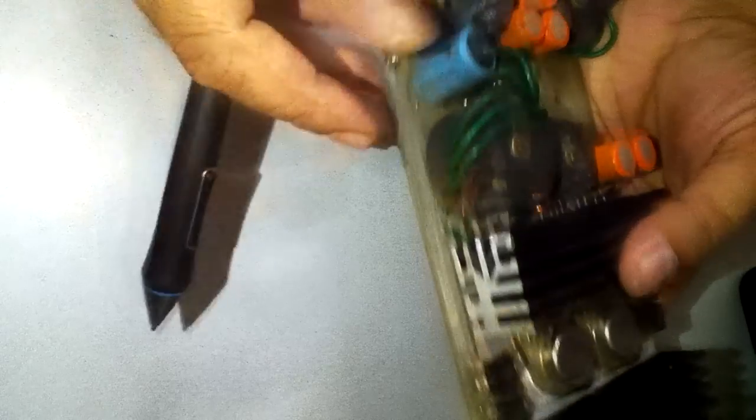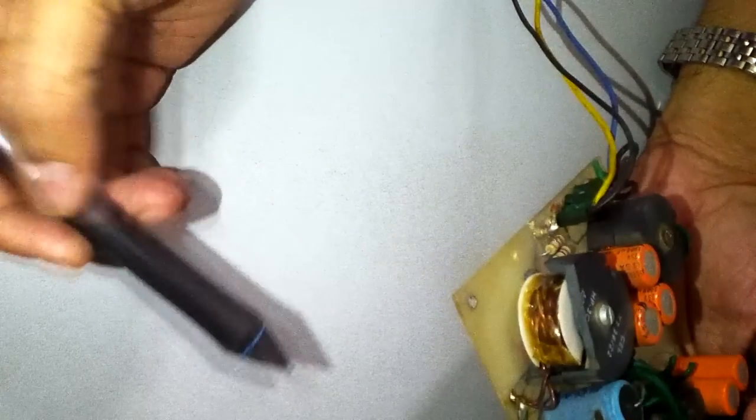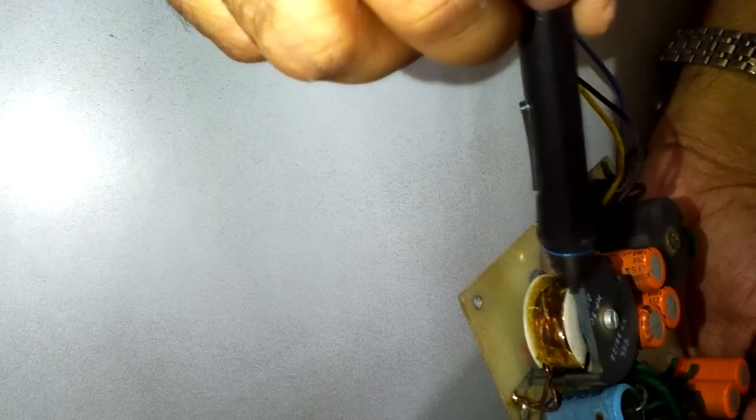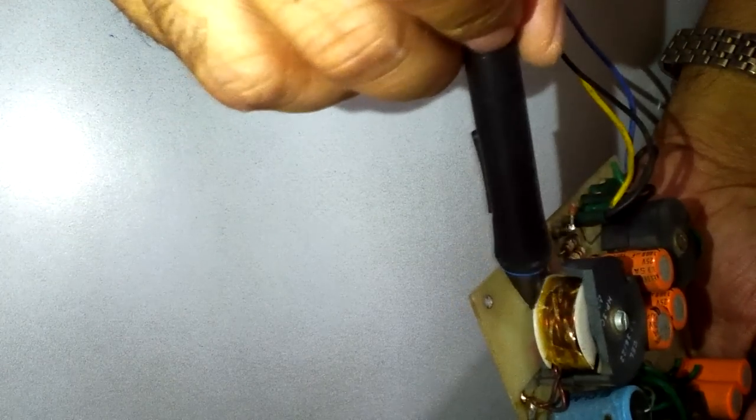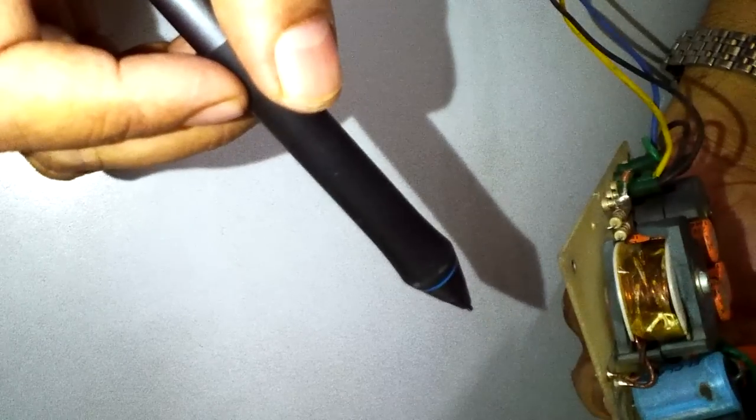In fact, you can get a much more clearer picture on a broken ferrite core here. You see that the ferrite core is broken, and within that is the former. This is a circular bobbin, and within the bobbin you have the windings, primary and the secondary windings. So something like this type of core material we will be using.